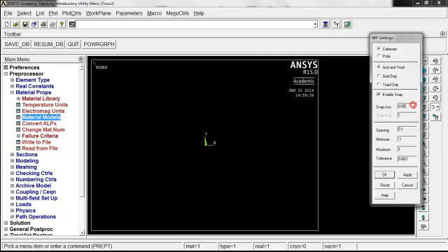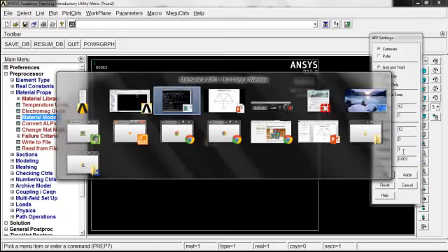I'm going to change our snap increment to 12. So this is in inches, so every snap or location on here is going to be every foot. We'll also do our spacing here at 12. All right, so the spacing is 12 as well. Minimum will be 0. The maximum, let's go back to our drawing.